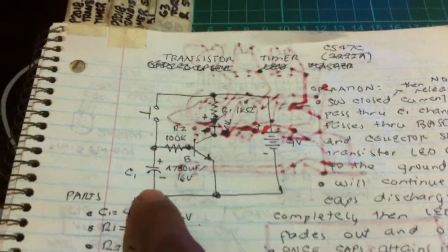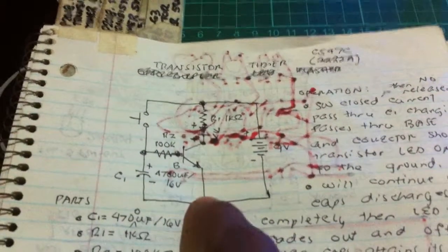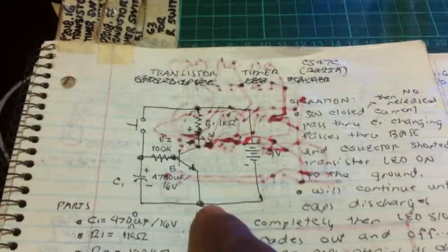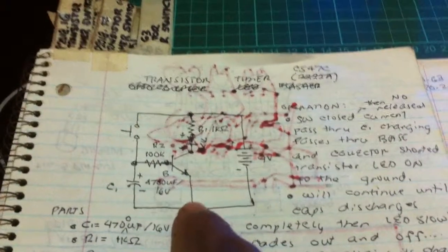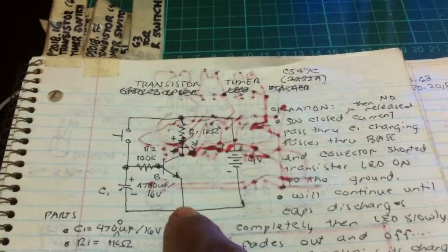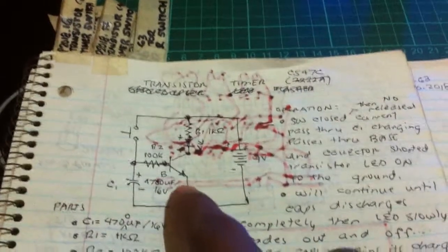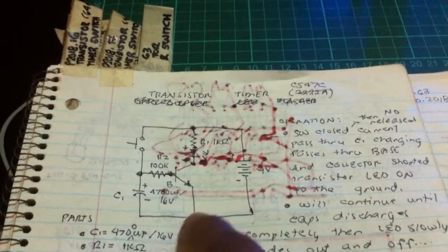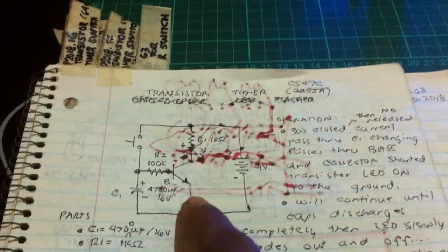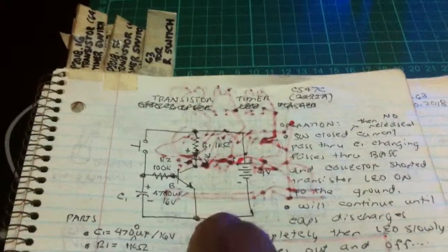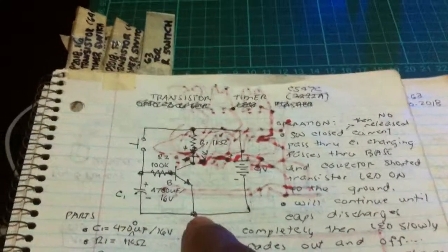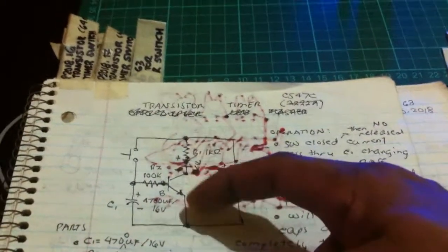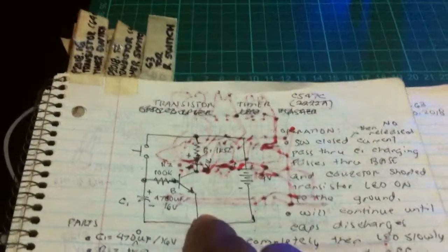Why? Because we have no resistor here. This circuit is not stable. We can call this a bias resistor, because without a bias resistor, or a pull-down resistor or sinking resistor for the transistor, a certain breakdown voltage and a leakage current will happen.